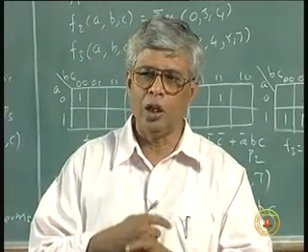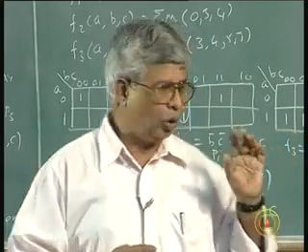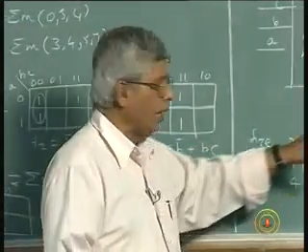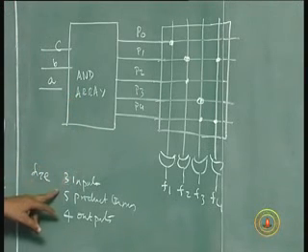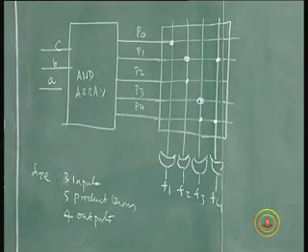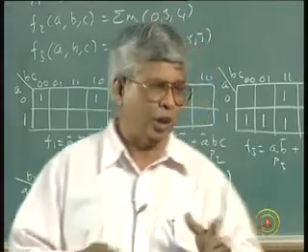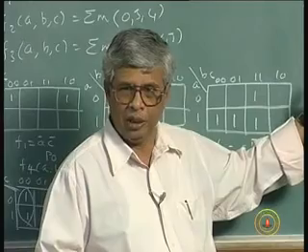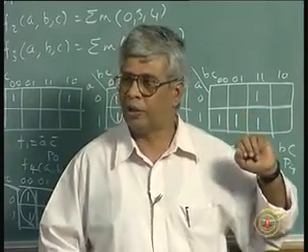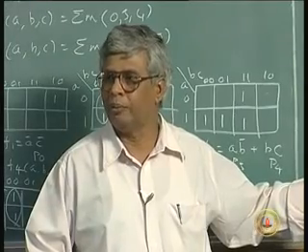It is not that you go to a shop for a particular device that you have in mind. I will put it the other way. I should have a programmable array logic which will at least have 3 inputs, at least can generate 5 product terms, and at least have 4 outputs. The smallest within that constraint, I will buy. You understand? Supposing no 3-input PLA is available, I will use a 4-input. Supposing 4 input is available, I will take that and use 3 of those inputs. Otherwise, how do I do this job?